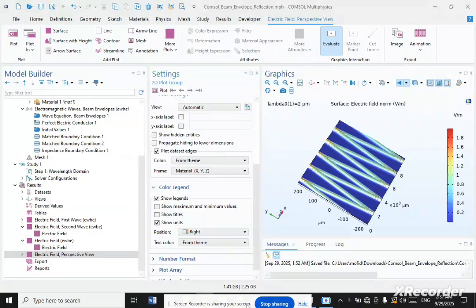It works by decomposing the electric field into a rapidly varying phase function and a slowly varying envelope function, allowing for reduced mesh size and efficient simulations of devices like waveguides and lens systems. The interface is part of the Wave Optics module and is suited for unidirectional and bidirectional propagation problems.